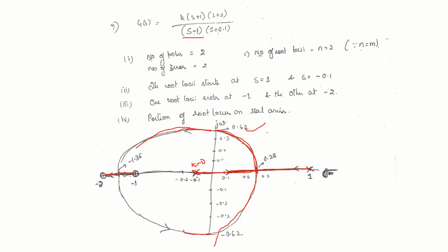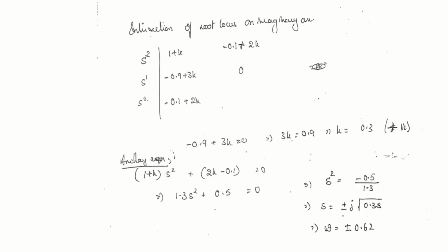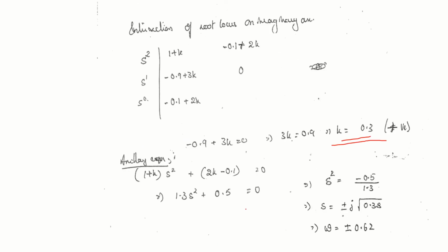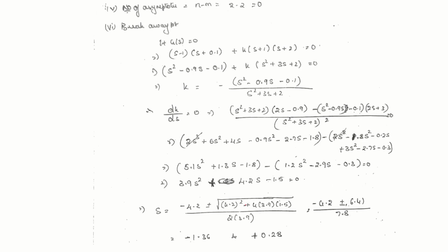I think this omega value, k value must be where? How much is that? This must be equal to 0. Okay, it's 0.3. K value 0.3. More than that, it will move to stable region. Okay, this is how we can work out these examples. But it is quite tricky. These are simple. In the next session, I'll show you some tricky examples.